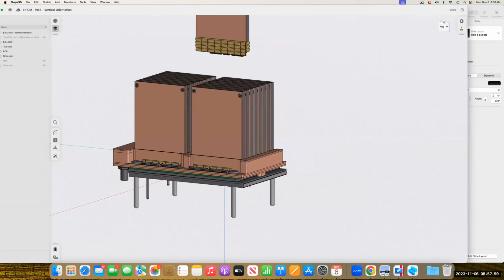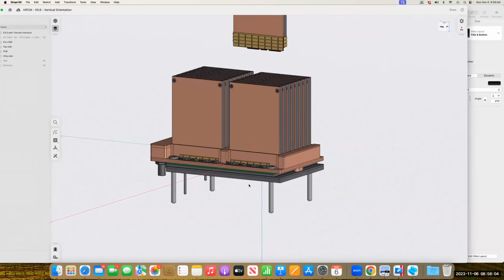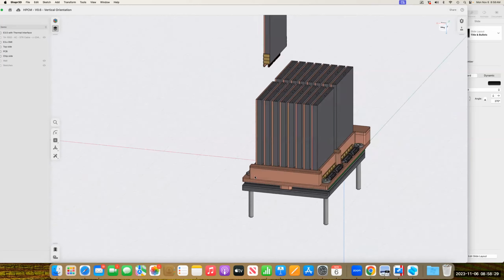Would that address the mechanical issues you're mentioning? Yeah, that's the kind of thing I'm looking for. I think it's a good direction, but whether it's sufficient to remove the board lock and replace it with an SMT solid tab, or even remove it, I think at the end of the day we still need to do the test, right? By the way, the design's good.